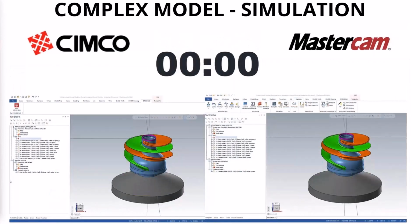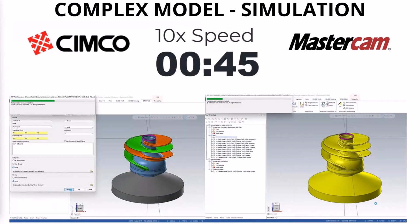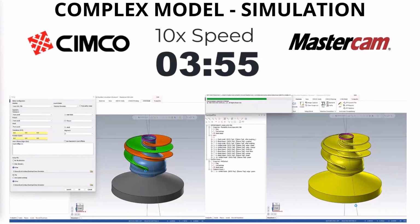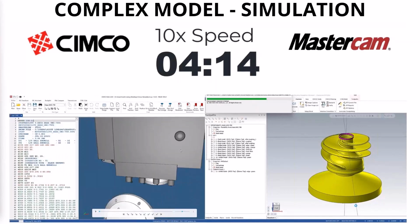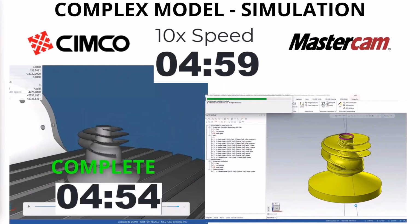100%. Let's take a look also. This is that same part, but we're going to run it through. Most people here, if you've bought a post from us, we've given you the option for a simulation. The module works driven simulation through Mastercam, and even now with some of the newer technology, we'll use an external post where we'll take the centerline code, run it through the post, feed it back into simulation. Still not true G&M code. It's a lot closer than it comes direct out of Mastercam, but it's still not the actual G&M code itself.